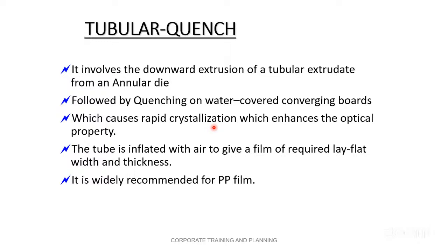And here we are using direct water cooling, chilled water cooling. There we cool the bubble by air, compressed air, but here by water. Therefore, it causes rapid crystallization, which enhances the optical property. Optical means clarity. Now, the tube is inflated with air to give a film of the required lay flat width and thickness. Yes, that we have seen.